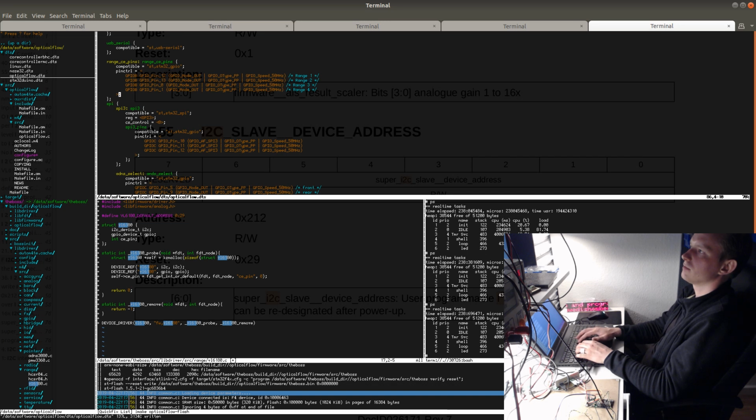And defaults, so this driver also supports defaults. They're going to be 0 on all of the pins. And I'm actually going to make the pins open drain. So we're just going to be pulling them low.